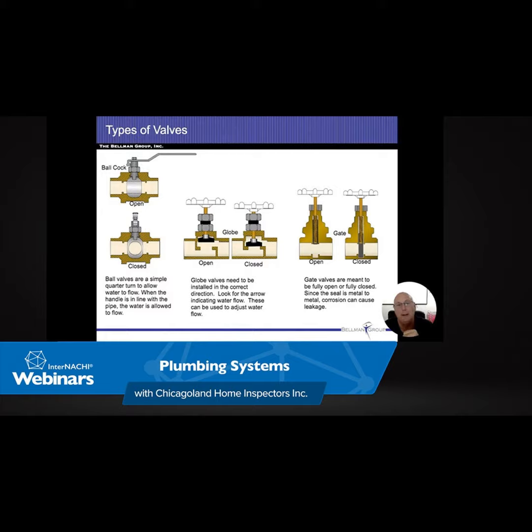Deep wells are going to either be drilled, most likely. They may be bored, but usually they're going to end up being drilled. Again, anything over 25 feet is considered a deep well. Around here, they tend to go around 50 feet, and I've heard them as deep as 500. Once the well is done and the pipes are there, they're going to actually insert the pump into the well, and they're going to drop it all the way down so it actually sits in the water.